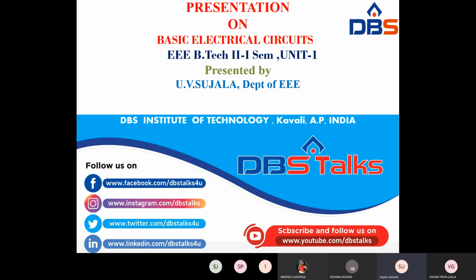Next, there is Kirchhoff's current law. What is Kirchhoff's current law? The algebraic sum of the currents is equal to 0. This is called Kirchhoff's current law. When you observe Kirchhoff's current law, it is also called nodal analysis. Kirchhoff's voltage law is called mesh analysis or loop analysis, but Kirchhoff's current law is called nodal analysis.